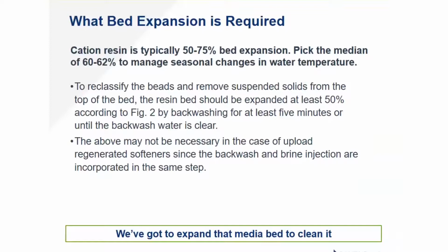Now, we're going through this bed lift to do a couple different things. One is to reclassify the beads or media and remove suspended solids from the top of the bed. The resin bed should be expanded at least 50% by backwashing for at least 5 minutes or until the backwash water is clear. This is a process in backwash.